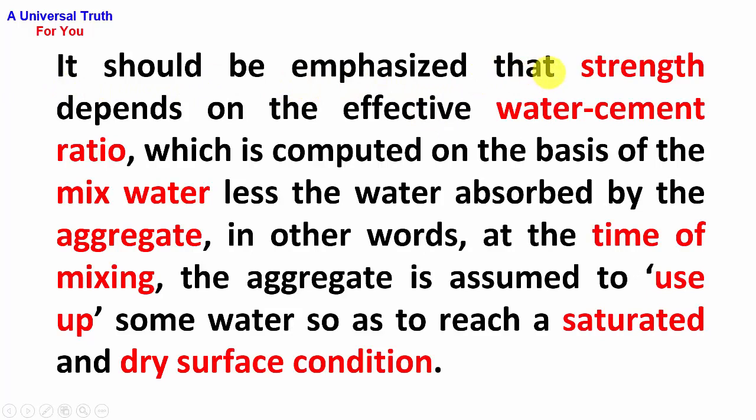It should be emphasized that strength depends on the effective water cement ratio, which is computed on the basis of the mixed water less the water absorbed by the aggregate. In other words, at the time of mixing, the aggregate is assumed to use up some water so as to reach a saturated and dry surface condition.